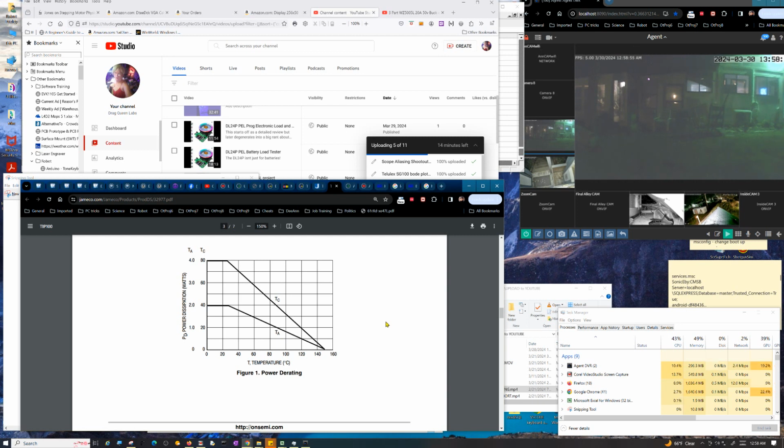Now, in a case when you have forced air cooling, where you might have a fan drawing heat out of it, the ambient temperature is going to be the upstream temperature. Again, I suggest a quarter of an inch to half an inch away from the component, in the air that's going to cool the component but hasn't yet.